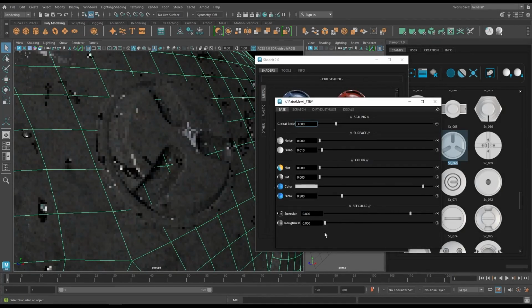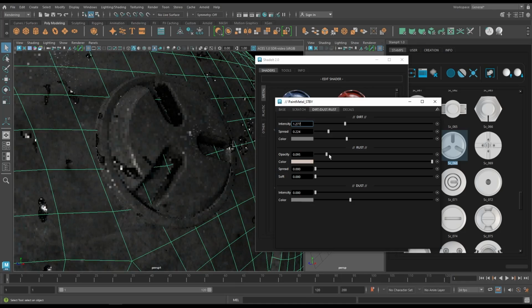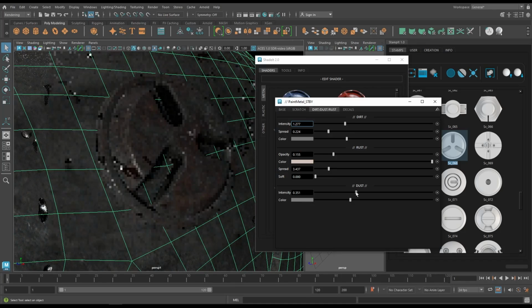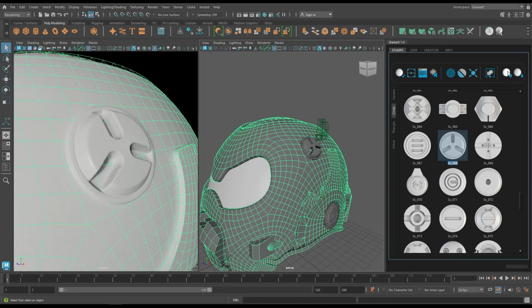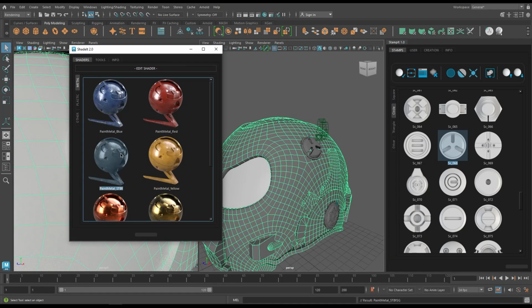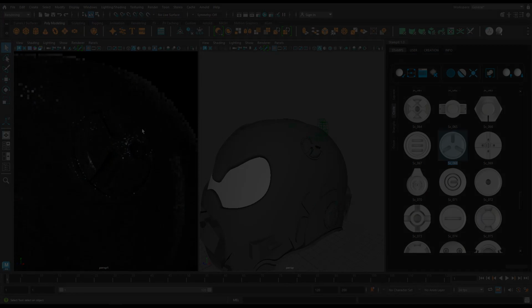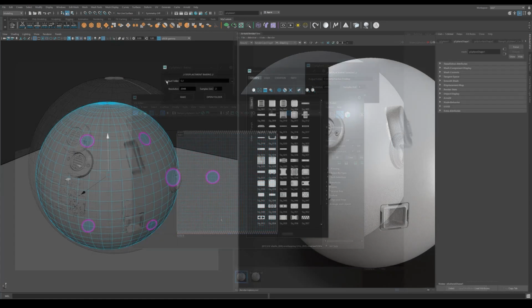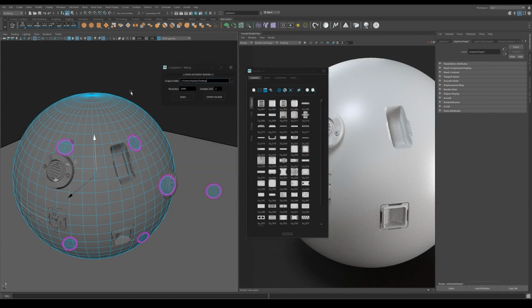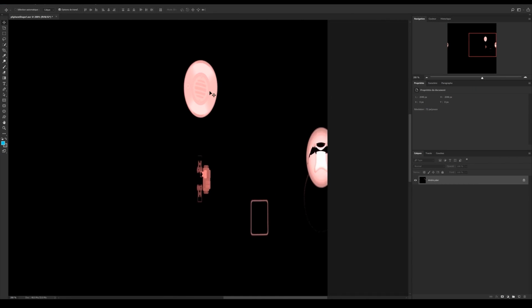When it comes to shading, it is a bit tedious, but it doesn't prevent you from doing it. It can be applied to any stamped mesh. So how does it work? You select the mesh and restore the information by clicking on Restore, then you shade it and you click Apply to transfer the information. When it comes to baking, Stampit allows you to bake information as a normal map for external software. This is the case if you are aiming to do so, but you would need to unfold UVs in this case. If you are wondering, the script supports both Arnold and Redshift.